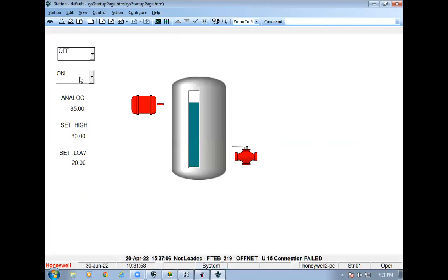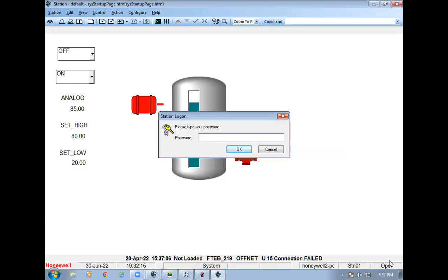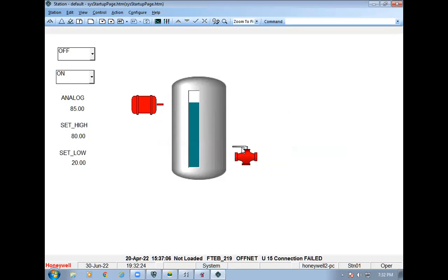It opens now. See, the set points and then levels have been showing here. So then here we need to change it now. See, if I click this now, it will be showing asset not assigned to the operator station. Means we need to change some manager. So in the right side below of the window, I'm having operator. In this operator, we need to give a password, MNGR. Okay. So after clicking in a manager, then click OK.